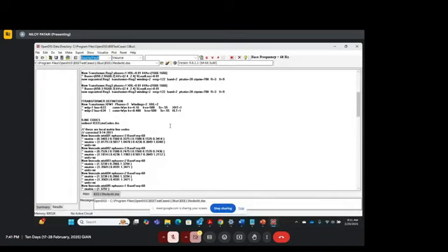Utilities generally don't have much visibility on the secondary side, and on the secondary side there can be huge voltage dips and voltage boosts that are not visible to the utility. That is a different kind of problem, but I'm just trying to explain what 480 volts really means. So this acts as a service transformer.